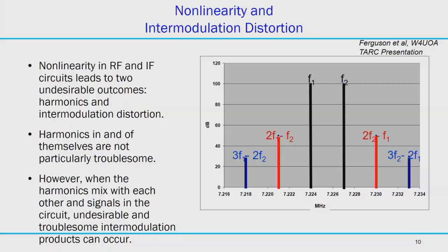So, even though we wanted F1, F2, or omega 1, omega 2 as the only signals that we're interested in, we can't ignore all the different signals coming out, third order, fifth order terms. This is 5 frequencies mixing, this is 3 frequencies mixing. They're all roughly the same thing, and therefore they need to be managed. When we design, we need to be able to tell other people up to what point this is a headache for you, or when you're buying someone else's system into your system, you need to check whether their design will not give you any headache further on.